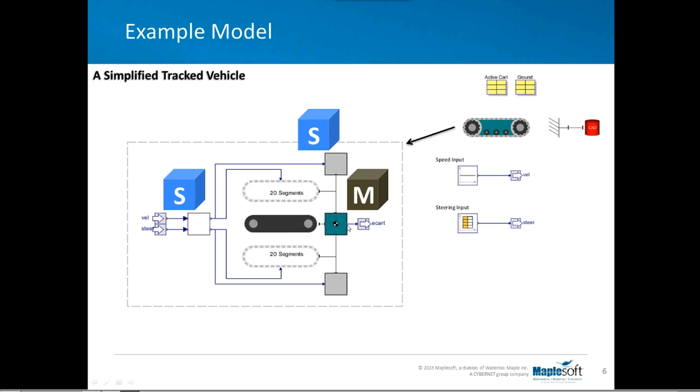This component in the middle incorporates the mass and inertia for the body. And these two blocks here, inside them there are components for calculating the forces that the sections of the track and the uneven surface will develop, and those forces are carried through by this connection back to the rigid body, which is the track itself. So friction and contact forces are calculated in these blocks, which perform signal processing or calculate mathematical operations on signals, and then the result of that is applied to the body through a force and moment component. So this subsystem includes multi-body components as well as signal components.